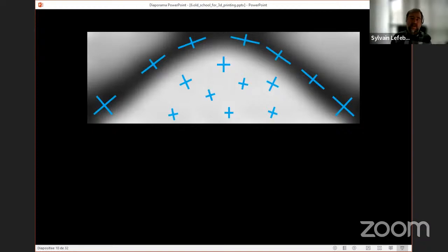Knowing that these solutions very often are actually not simply about density. In every point of these domains, you get an elasticity tensor, and you can also have, if you choose so, information about the anisotropy, for instance, of the material. And so the tiles that I showed before are not super convenient when you actually have changes of orientations like that. So it's a very interesting problem how you get from this coarse scale solution that is more general and has also a directionality in it to an actual structure that will implement this.